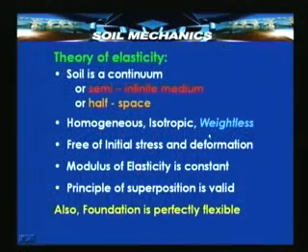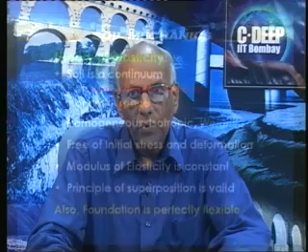Now, one more important assumption we are making about the medium, and that is it is weightless. Let us see the importance of this. Why is the assumption of weightlessness important? It is important because we are interested in the incremental stress that is being caused by the load that is applied externally on the surface of the ground.